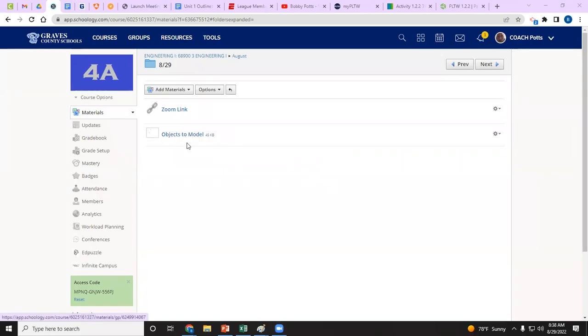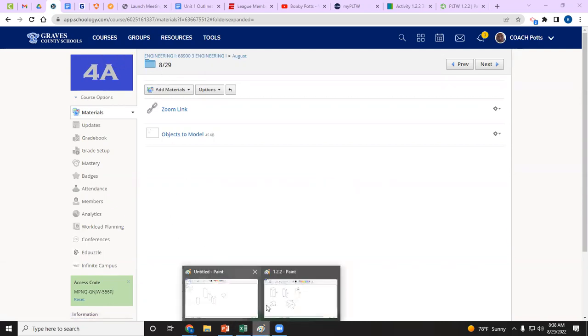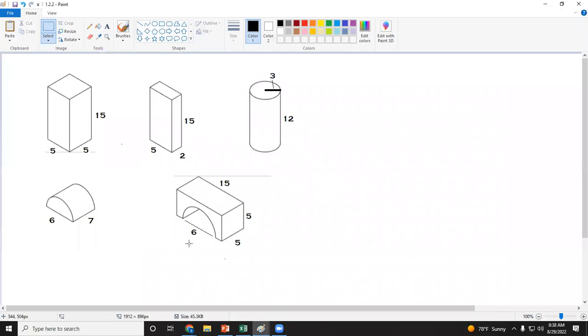Okay, guys. So today in our 829, we are going to look at building these 5 objects on Onshape. Okay, we've got this one here, just a square. It's been extruded, rectangle been extruded, circle been extruded, half a circle extruded in the other direction. And here you've got a rectangle that has that half circle chipped out of it. Okay, creates this arch. So starting with this one, there's a couple ways you can do it.